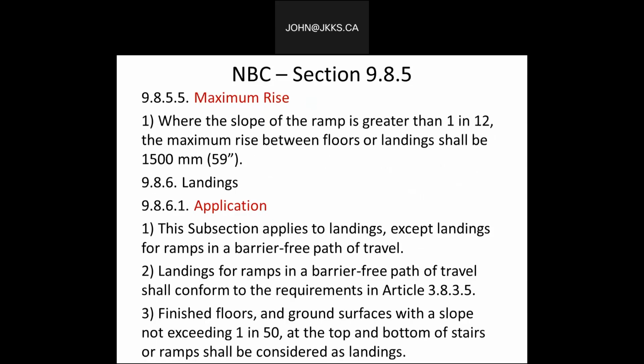What about maximum rise? Where the slope of the ramp is greater than 1 in 12, the maximum rise between the floors or landings shall be 59 inches. And then we get to landings.